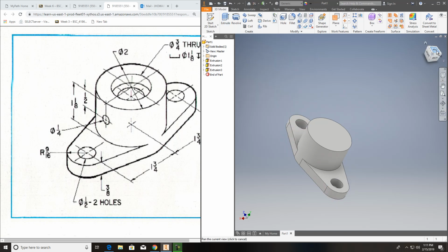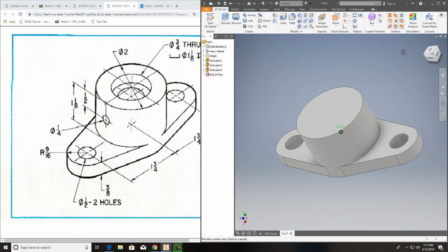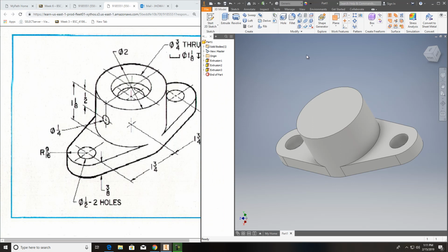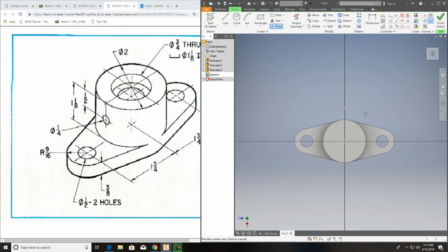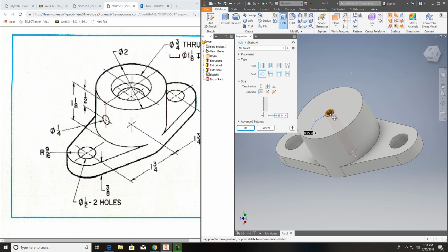Gone, that's good. Now let's go here and put us a hole at the top with a counter bore in it, and 3/4 inch through, 1 1/8 inch diameter counter bore. It's going to be 1/4 inch deep on that counter bore. So I do a new sketch, click the face of it. I want to put me a point right in the center of it, and then finish my sketch out. And then I want to do a hole command, and just choose that hole right there.